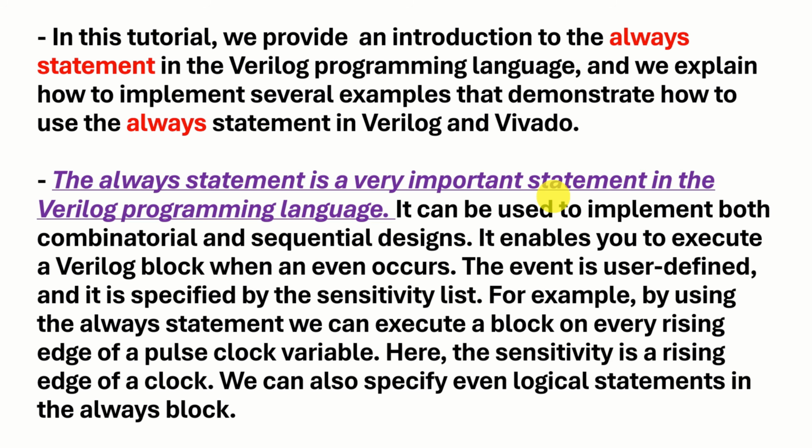In this tutorial, we provide an introduction to the always statement in the Verilog programming language, and we explain how to implement several examples that demonstrate how to use the always statement in Verilog and Vivado. The always statement is a very important statement in the Verilog programming language. It can be used to implement both combinatorial and sequential circuits and designs.